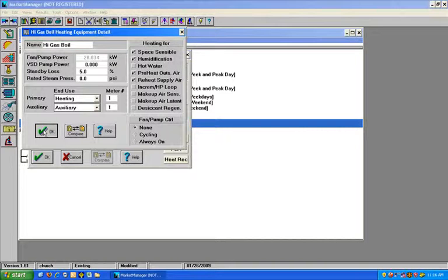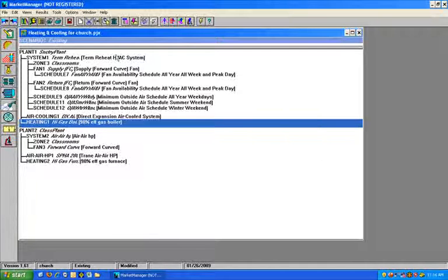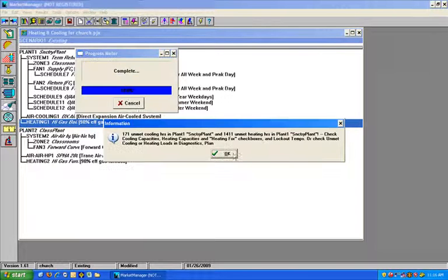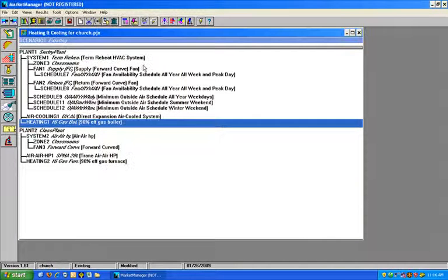And it's not just going to magically do it for free and not count it. You'll get a message that says it. So this is a terminal reheat, good. So if I simulate this, it's going to say I have unmet heating hours, and that's because one of the reasons is because I'm not doing the reheat. And this is a terminal reheat. Okay, so it'll tell you that at least.